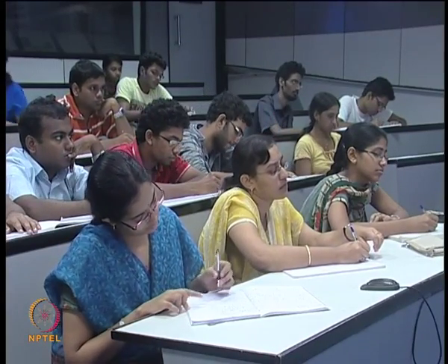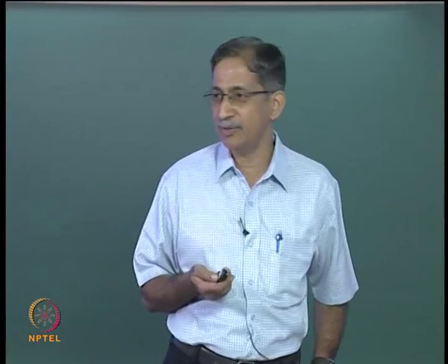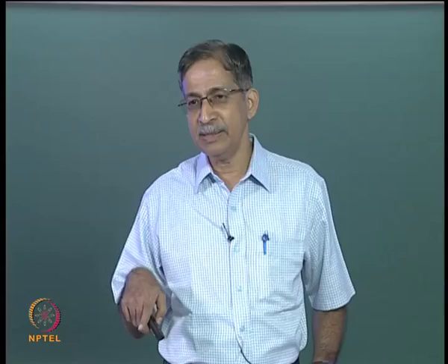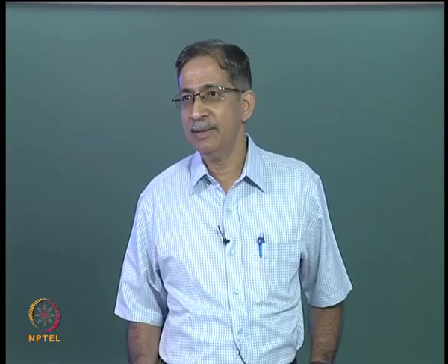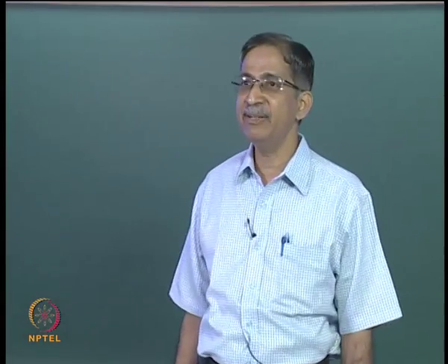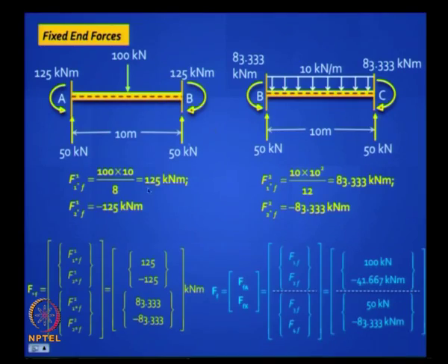And you have to do it manually. You can't use the TF transpose. So you remember 1 and 2 are at B and 3 and 4 at C. So you have to get the vertical reactions. If you look at F1F, it is the sum of 50 and 50, is it not? So you have to see what adds up at 1. So you get 50 kilonewton here, you get 50 kilonewton here, they add up to the coordinate 1, and that is how you get 100 kilonewton here.